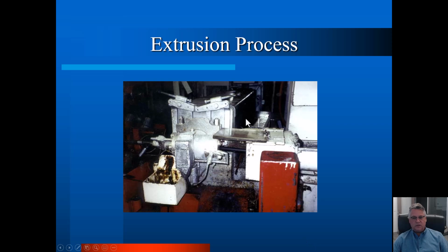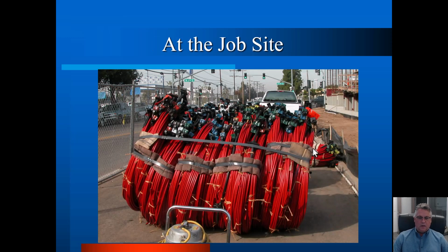So this is the plastic sheathing being applied. This is hot molten plastic being placed around the strand as it's coming through. And then that strand and plastic will go into this cold water trough, which shrink seals it to the strand. And voila, this is what it looks like, delivered to the site. So again, we can be at any length we need to be. It can just coil up and get placed on a truck, and that's how 300 feet of post-tensioning tendons gets